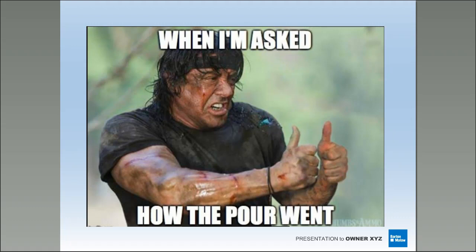Make sure they're using that edge tamp, because there's a misconception that you're going to knock the fiber down and it's useless. No, I'm just bringing more cream up that I can polish to keep that fiber at bay and keep it covered. But the integrity of the fiber and the purpose it's there, it's all still there. It's doing exactly what it should be doing. I hope that helps.